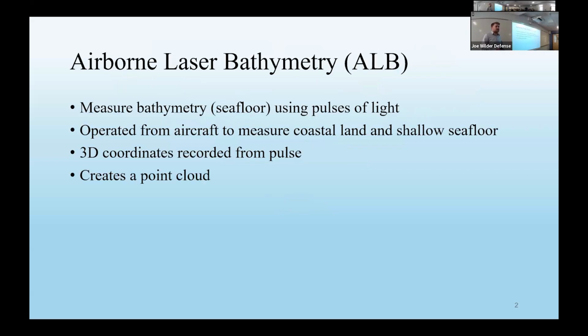So first, I want to talk about the data that we're working with. What is bathymetry? We can just think of it as the seafloor. So we're looking for a way to measure the space of the seafloor. And we do that using airborne laser bathymetry, which we can think of as just LiDAR. It's typically operated from an aircraft or a drone, something of the sort, and it sends out pulses of light. Those pulses of light can record the land, and a special type of LiDAR is also able to go through the water and actually get the bathymetry.